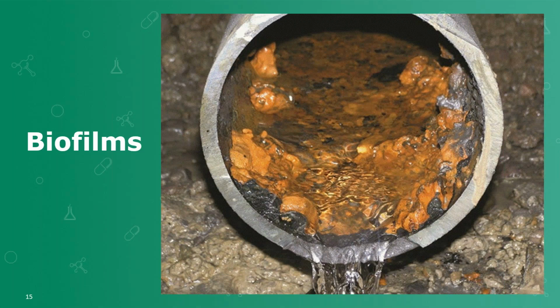So just moving on now to biofilms. We've got a great picture on the slide there of a biofilm formation in a pipe. A biofilm comprises any group of microorganisms in which the cells are bound to each other and bound to a surface. The fundamental concern is with water systems. As these microorganisms adhere to the surface, they start to produce extracellular polymers, and these facilitate the adhesion.